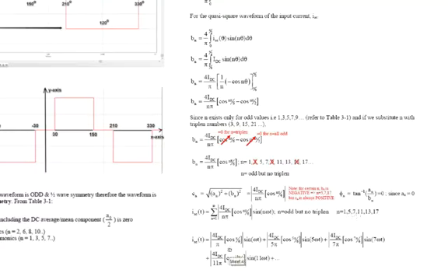And finally, your Fourier series equation is 4 IDC over pi cos pi over 6 sine omega t, and then the next amplitude will be 4 IDC over 5 pi cos 5 pi over 6 sine 5 omega t. Next will be 4 IDC over 7 pi cos 7 pi over 6 sine 7 omega t, and the rest. So this is the Fourier series of the quasi-square waveform.